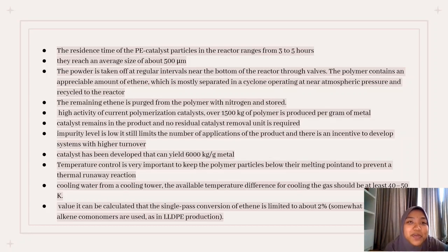Temperature control is very important to keep the polymer particles below their melting point, 390 Kelvin and 373 Kelvin for HDPE and LLDPE respectively, and to prevent a thermal runaway reaction.